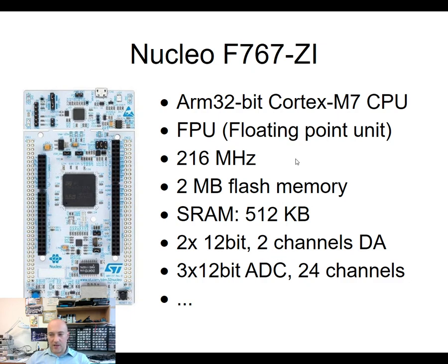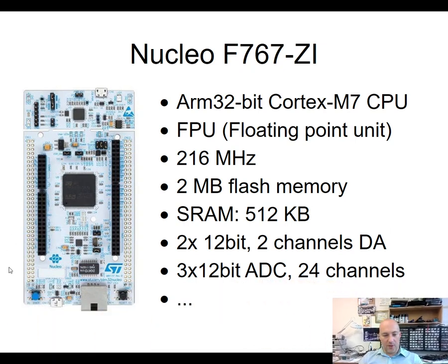You can see that here on the bottom we have a USB port. So if you write the firmware for it, or if you download some example, now this microcontroller can be used as USB host. So for example, you can connect a flash drive and you can access the files through this connector on the flash drive, and you can use that as a storage, and you can store your user data, your files, your images, whatever, on this flash drive.